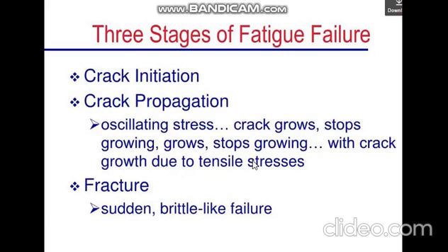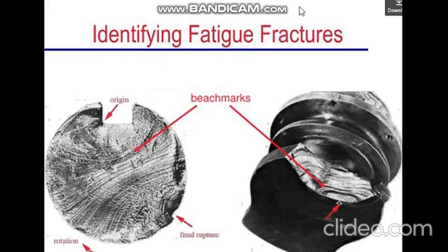Opening, closing. That's why those striations that I showed you in that diagram, those beach marks, are forming: opening, closing. Okay, like that the crack propagates. Till when? Till that time when the cross section area can no more bear the load that is coming. Then there will be fracture, and this fracture is a sudden brittle-like fracture when nobody can expect. Think of it, if a railroad axle breaks in the middle when you're traveling, the train comes to a standstill.